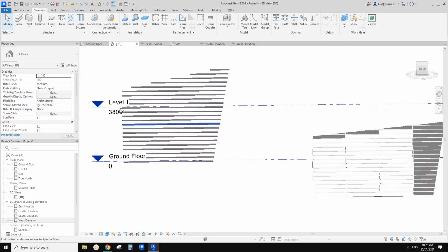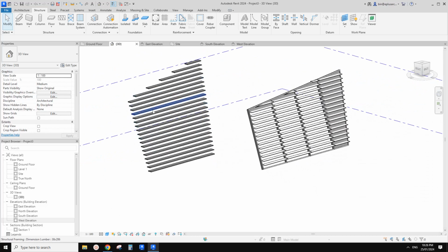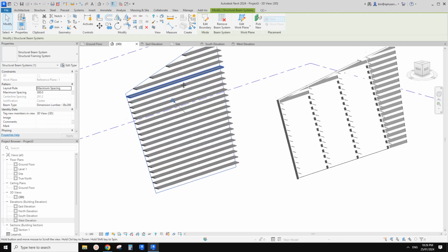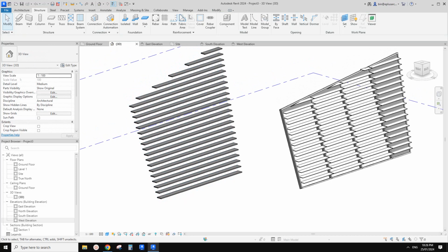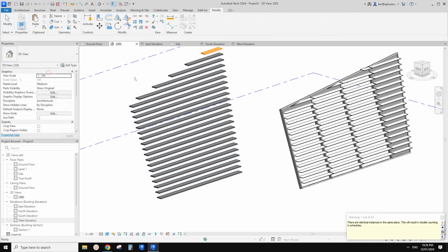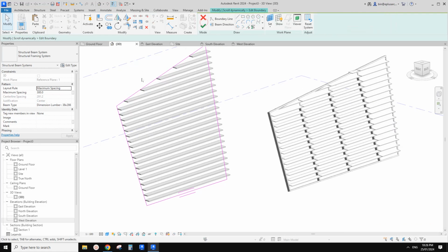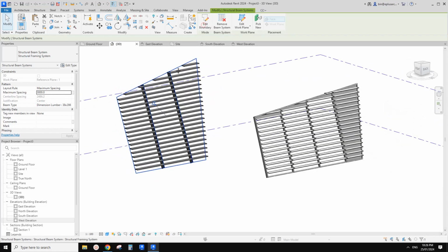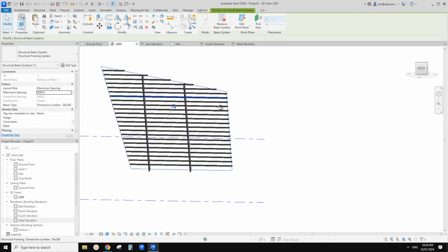Of course, if you want to have some vertical ones, it's quite simple as well. Once you have this one, usually what I do is Control C, and then paste in the same place, edit sketch, and then pick a vertical one and change the spacing to maybe 3 meters. Okay, I'll use same, and then we have some in the back.